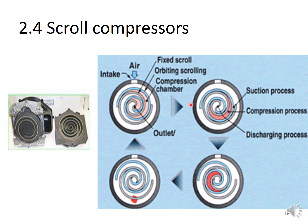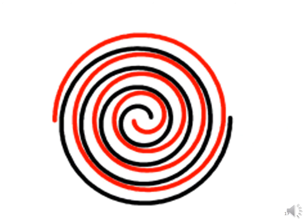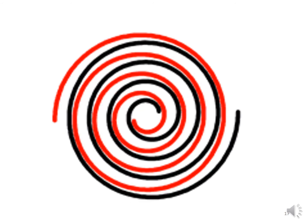Okay, this is called scroll compressor, like a spring in our watches. If you see a hand watch, there is a spring inside which makes the hands of the watch rotate, the hour needle and the minute needle. Same like this one, scroll compressor. So it compresses through this, and from the center it will deliver. Now this is the action. You see the action. Air goes here, it pushes the air and delivers here. Okay, this is how a scroll compressor works.